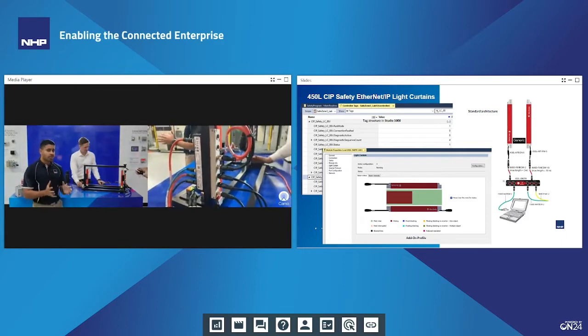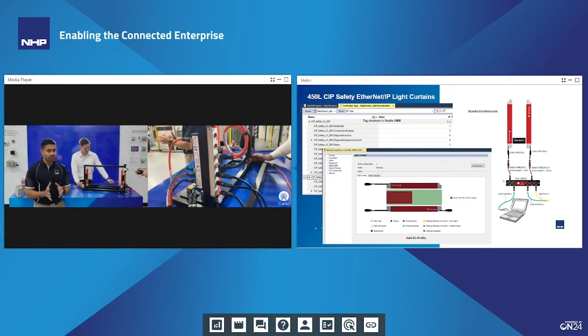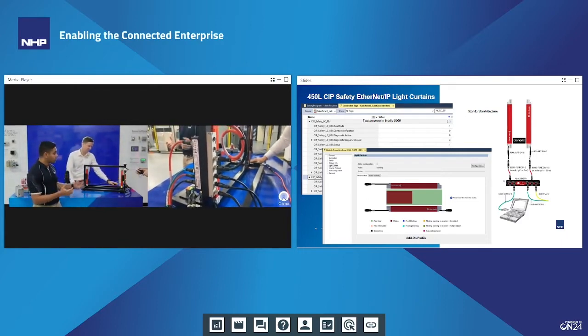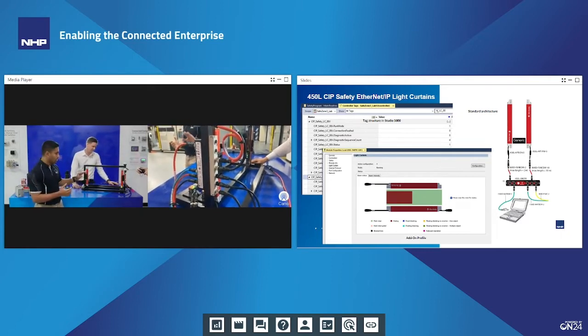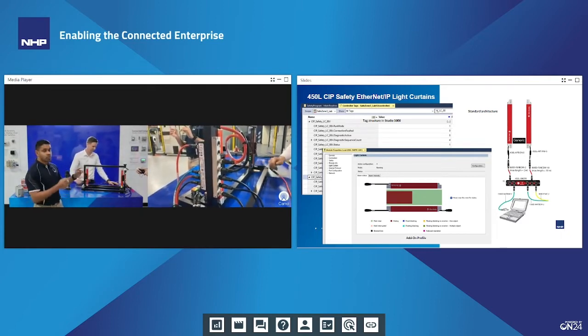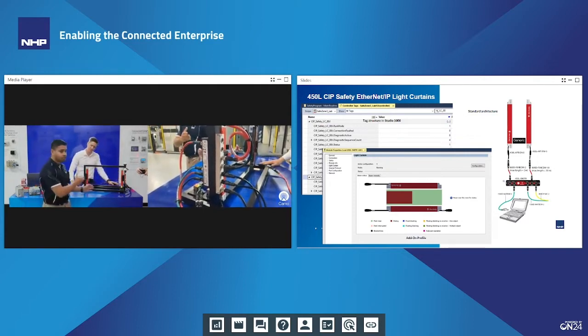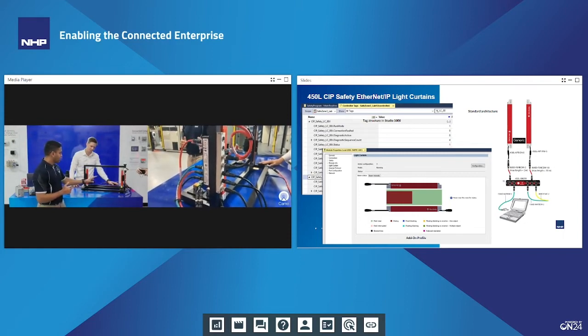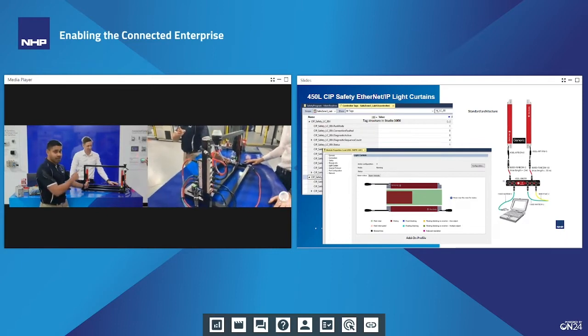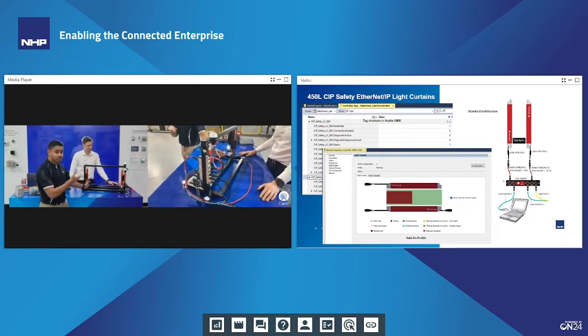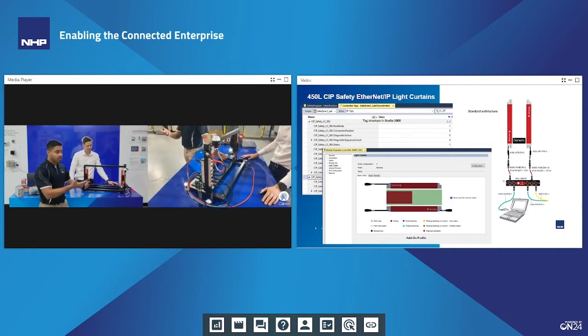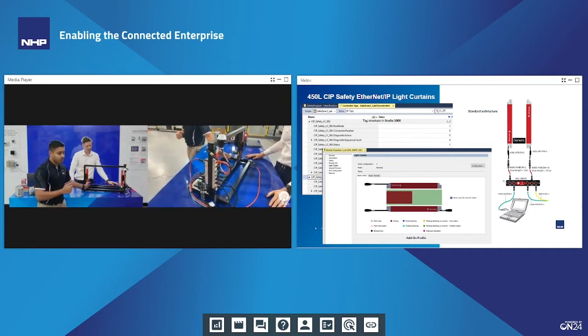Yep, that's the muting distribution block, again an on-machine device. It's IP rated, which we use to connect our muting sensors and also to showcase whatever outputs we have. Now, let me just show you. I've got this configured for muting, but since we've broken the light curtains, it's not going to demonstrate. However, we can see that the device is being output from that. So what I've done is I've induced a fault by creating a wrong muting sequence, and we can see our muting light flash right now. All of this is done programmatically.